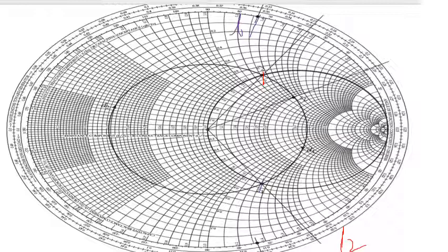Now, this is for open circuit. Suppose the same question they had asked you for short circuit. What will you do? Same way, continue with the problem, but the only difference is that you will neither subtract nor add. The important points which were there for the shunt configuration, the same thing continues over here. But for the open circuit, when you're doing series combination, whenever it is greater than 0.25 lambda, you need to subtract.